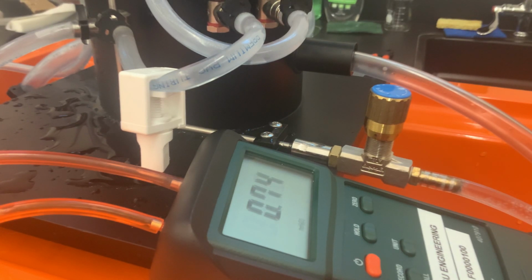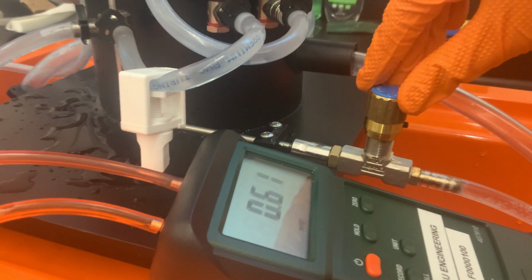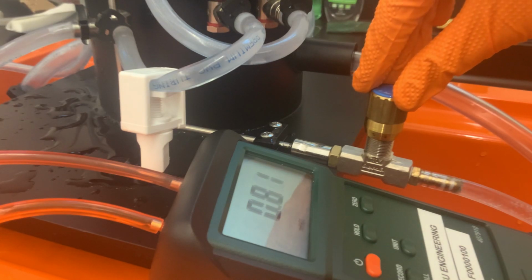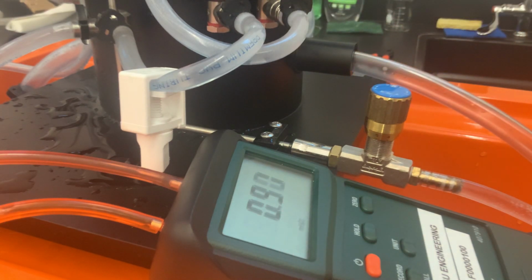We have taken one data set. Now what I have to do is change the flow rate. So I am increasing the flow rate. So you see the head loss went up from 0.8 to now 0.9. So again, I will take this major head loss, meaning if I increase the flow rate, the loss is more.